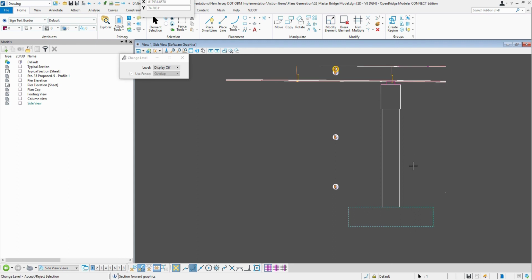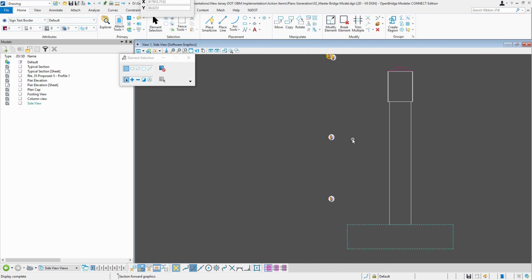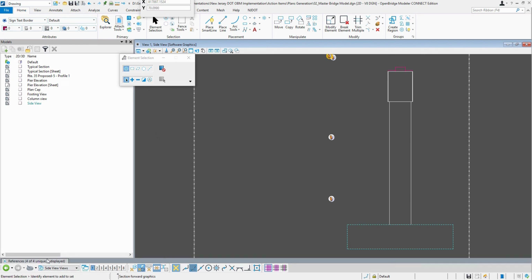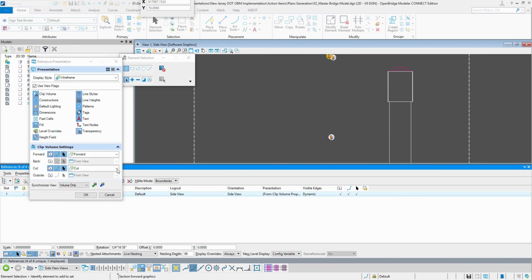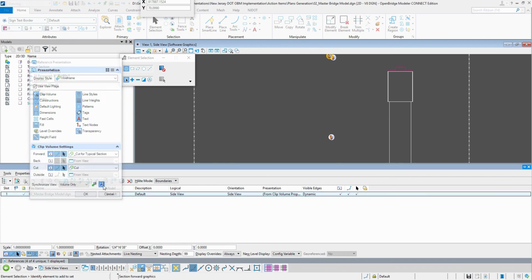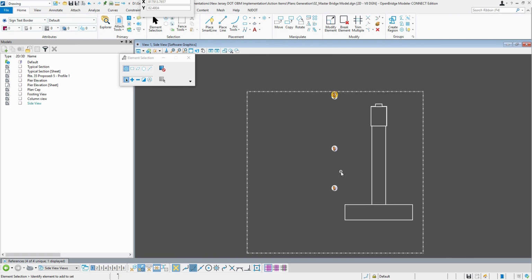So as I said, you can turn off the levels by element, so you just only see the actual pier with the beam seat. And then control the display rules or how you want to see that in your reference file. And the display rules are preset. You can configure your own display rules for your project too. We included some in the standards. So like for example here, all the solid elements is going to show like that.